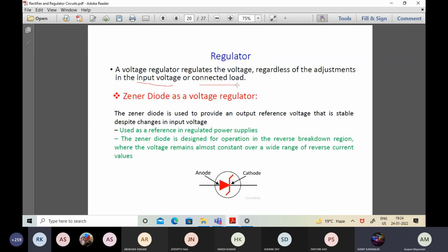In normal diodes, it is just the normal carrier path, overcoming a barrier, as we all know. Now this quantum mechanical tunneling of electrons, leading to the Zener current IZ, is mainly effective when we put the Zener diode under reverse bias.